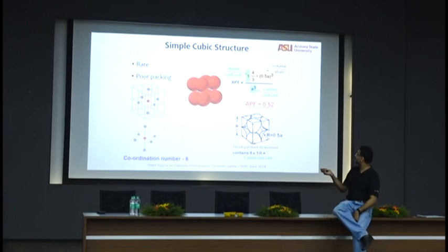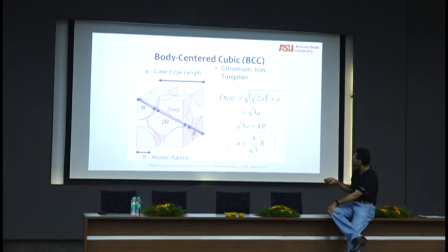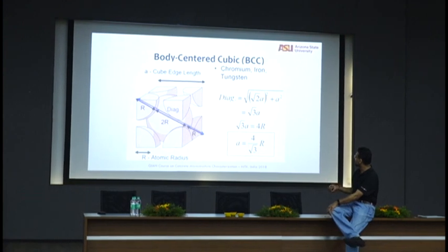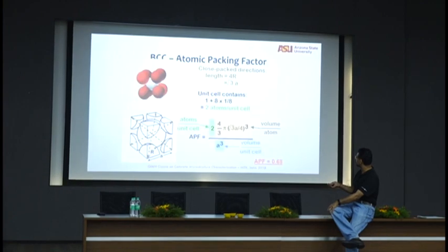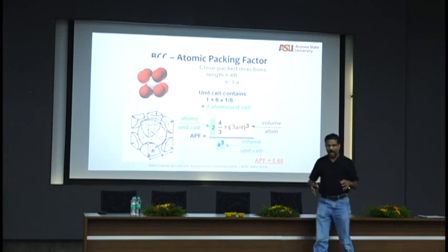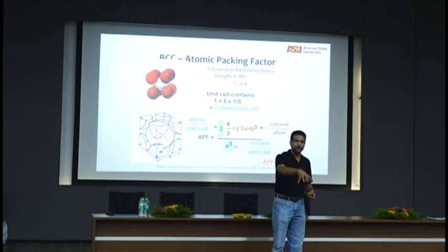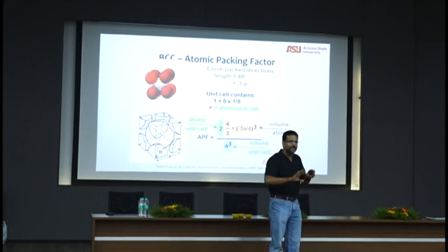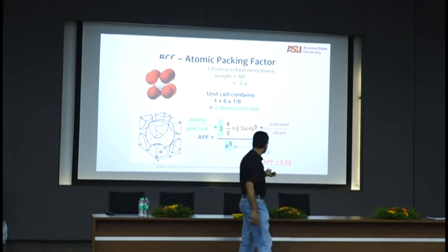That's one thing. Now if I simplify it into what is called the body-centered cube, it's a little more complicated. So again, all the corners have 1/8 atom. There is one big atom right in the middle that has displaced the particles so that the distance now is a little more. And you can do all the calculations, I'll skip that, you can look at it. You will get a packing factor of how much? 60. So basically, I put exactly those cubes plus I put one particle in the middle of the cube. Putting one particle in the middle of the cube where I have all the particles makes the cube larger also. Right? So think about that. So effectively, my packing becomes 68%.